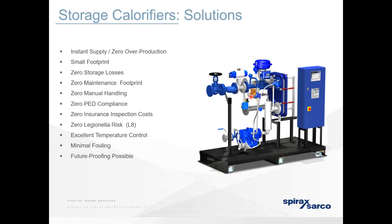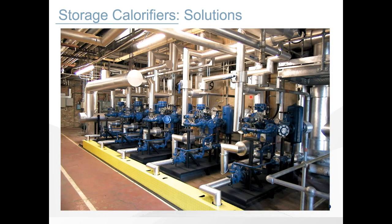I know we show our easy heat unit there, but there are other heat exchanger units you can use. A heat exchanger is always going to be more effective than a calorifier because, like we said, it's instantaneous, plus the other reasons listed there. So here's an example of those units sat in place instead of those tanks. Does anybody have any questions there?